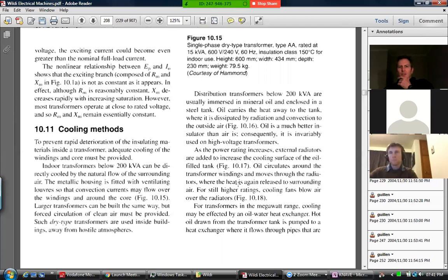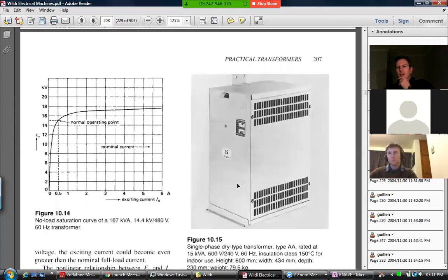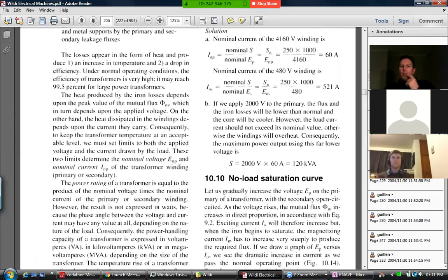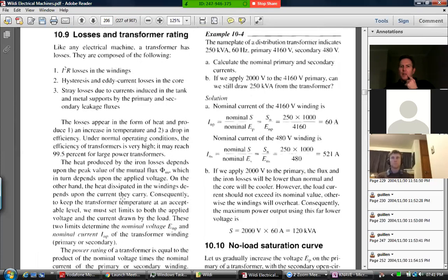They use the lamination so that you don't have too much eddy currents. They design the thing to operate here just at the edge of the saturation region. If you go up into this region over here, suddenly you get currents that are produced very easily because the magnetic circuit doesn't need to kind of absorb that current to make more magnetism because it can't make any more magnetism. So you get some current spikes and things if you operate out here somewhere. So we're trying to avoid that. But we'll pick it up next time then.